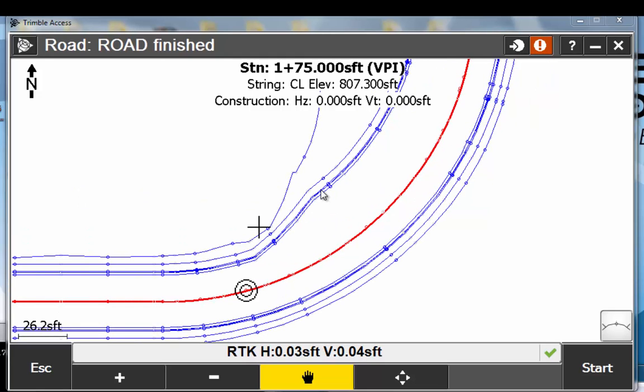Yeah. I haven't done it in a while, worked with survey guys, but I remember with previous times we've done this export of road with the frequency you were talking about, how it shows every station that we sample a corridor at. Is there a way, instead of making a copy of your corridor or something and changing that frequency, to get that as an output or something that they can back off of if they don't want all those? So you want to be able to dial down the frequency of your corridor once it comes in here.